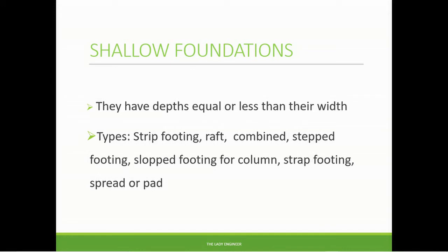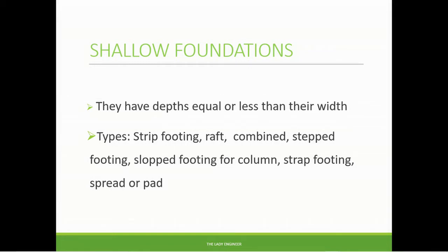Let's talk about shallow foundations. As the name suggests, these are not as deep. They have depths equal or less than their width. Most shallow foundations are suitable for stable ground. We have several types of shallow foundations, which include strip footing, raft foundation, combined foundation, stepped footing for columns, sloped footing for columns, strap footing, spread or pad foundations.